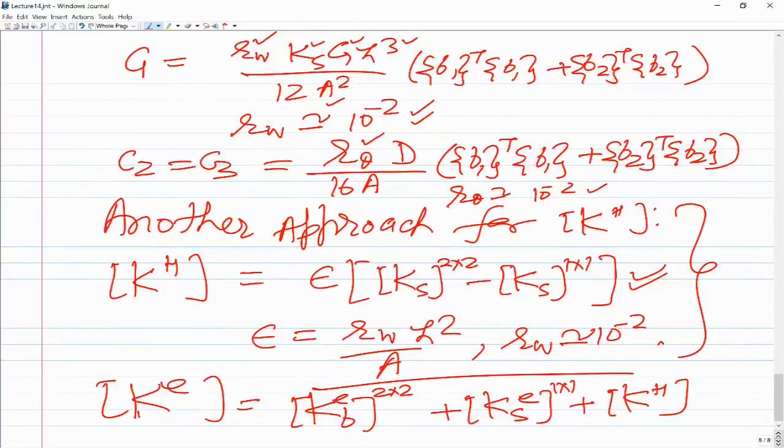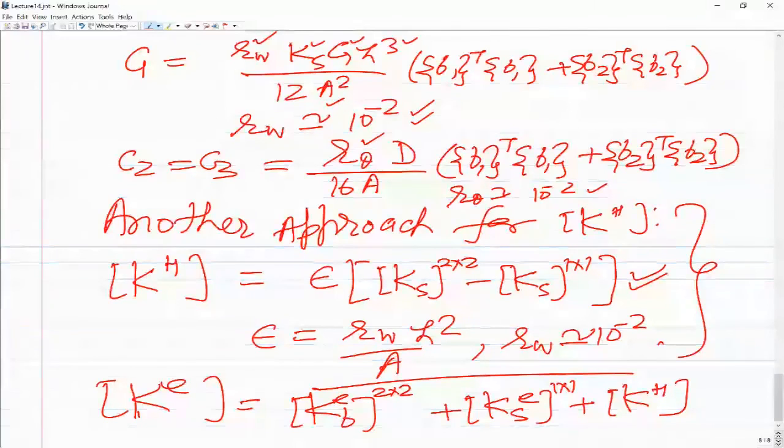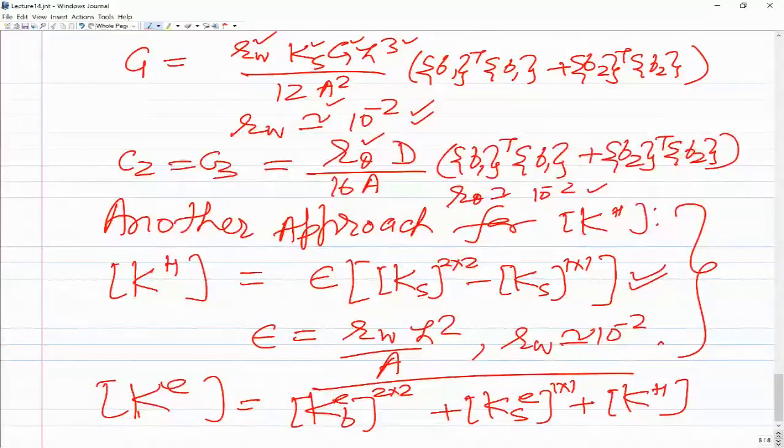In this case, if you look at the diagonal elements, they come out less, not more. That is why we have to add an additional stiffness. And this additional stiffness only affects the hourglass modes. It doesn't affect the rigid body modes. So why is it coming out less? Is there any specific reason? You have to numerically evaluate and check. I don't have a reason as of now. Okay, sir.